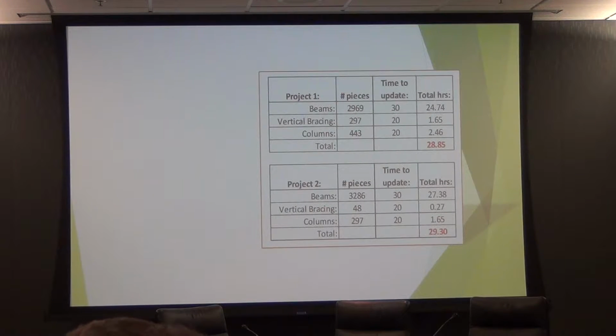So can you afford to spend 15 hours learning the RISA Revit link? Yes, it was painful to do that, but now you've got that knowledge in your tool kit, so that you can go to your next project and it takes you 30 seconds to go back and forth between RISA and Revit. Or you're modeling it and you say, well, I already know that it's going to break in these ways, so I'm going to fake it in these ways, and when I come back, I'll just mark up those 6 beams by hand, something like that. So anyway, point is, yes, it does take some time to work the kinks out of this workflow to share data between these pieces of software, but I think in the end it pays for itself.